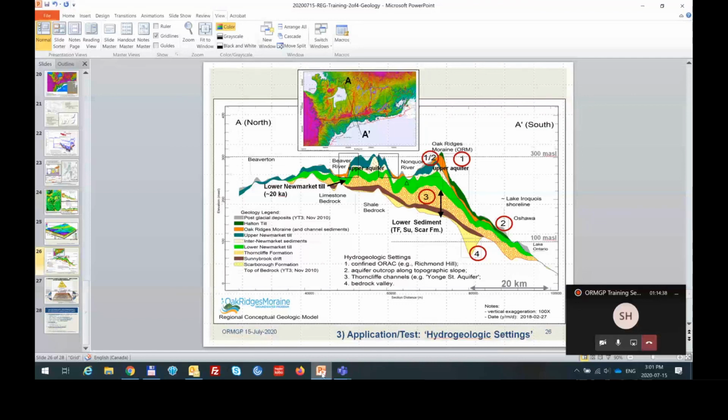Yes. Well, okay. So we are incorporating data sets from many locations. And if you think about it, the research, obviously we emanate out from high quality locations, OGS, GSC, landfill investigations, but we also bring in Ministry of Environment, Conservation and Parks water well records. And like any data set, there are errors, and there are errors related to a lot of different things. There are errors related to data input. What may have been put in as meters was really meant to be feet.